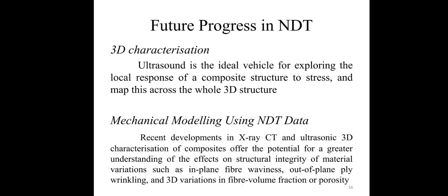Recent developments in X-ray CT and ultrasonic 3D characterization of the component's composition offer the potential for a greater understanding of the effects on structural integrity of material variations such as in-plane fiber waviness, out-of-plane ply wrinkling, and 3D variations in fiber volume fractions or porosity.